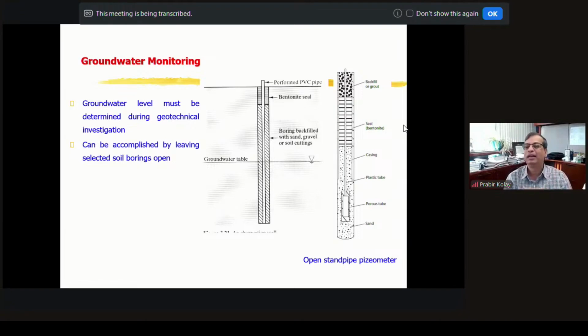If there is clay type soil, water will not come into the borehole immediately. So we need to keep it for 24 hours and then measure the water when the water level is steady, meaning that all the surrounding water has already come into the borehole. Again, there are different perforated pipes, and sometimes we need to use a steel pipe with grit, and sometimes you also use geotextiles.